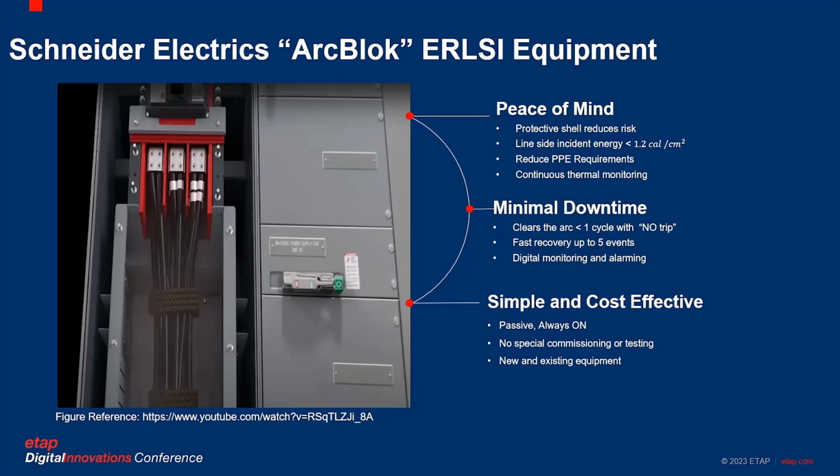In addition to this, the interruption of the actual arc is done passively. And when Schneider Electric refers to this being done passively, what this means is that there's no circuit breaker being triggered to clear the fault. So when this is done passively, the beauty of it is that there's no interference or any influence in the coordination of the system. We're not introducing miscoordination like we did with maintenance mode, for example, because we're doing this passively.